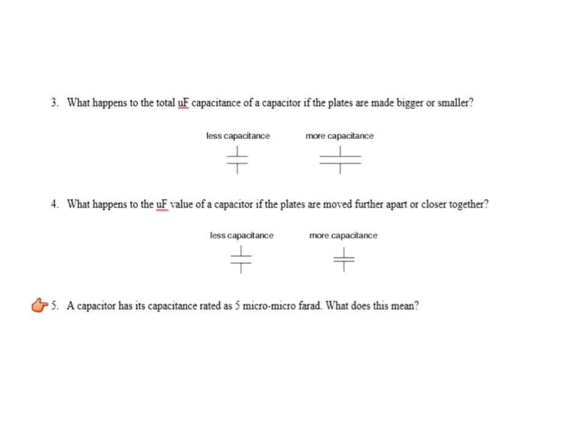An old unit that you might see in a CET exam is a very old unit called the micromicrofarad. When you see that, all that is an old unit for picofarad, because picofarads are 10 to the minus 12th power, and microfarad is 10 to the negative 6. So a micromicrofarad would actually be 2 10 to the negative 6s, and that would be 10 to the negative 12. So it's just an old term for picofarad.